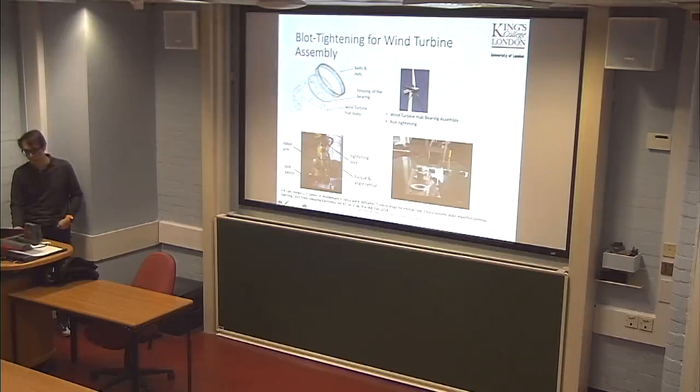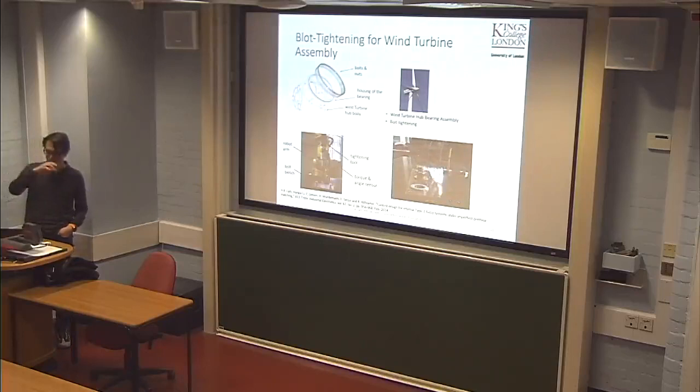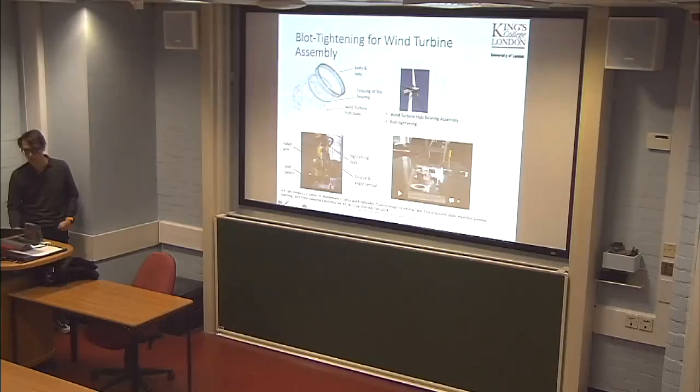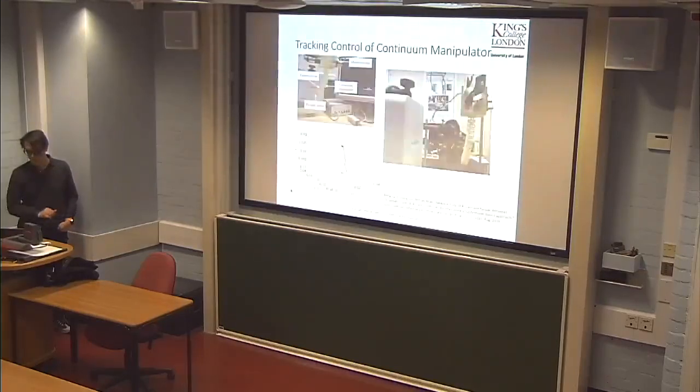In the lab, we have the bolt tightening tools mounted on the robot hand, and this is one of the experiments we have done. We programmed the robot to pick up the bolt and then run along the nut, and finally we are able to tighten it. This interval type 2 fuzzy logic system controls how much torque we are going to maintain. If you would like to know more details, just refer to this paper.